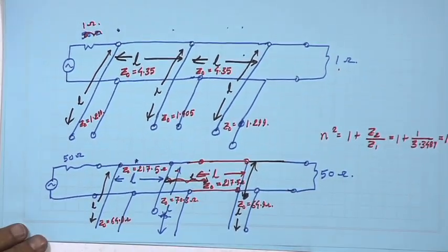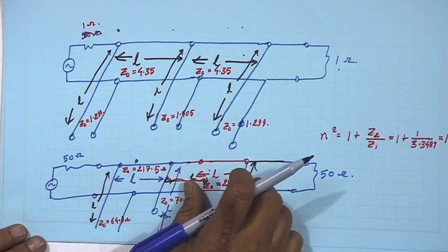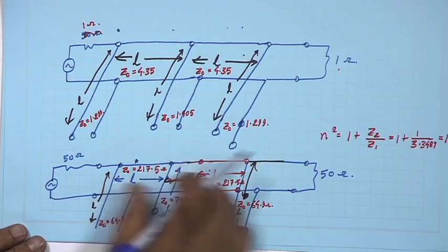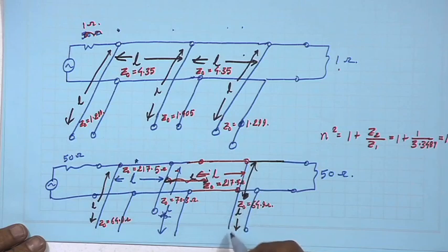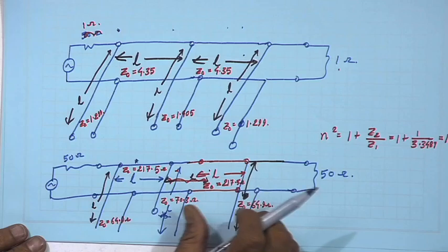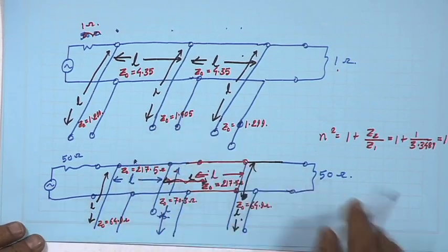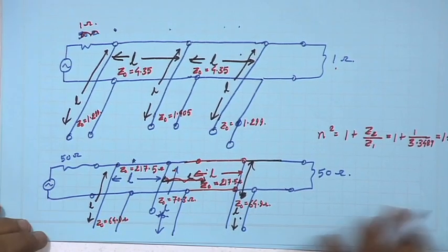Okay. So you see I have now 3 stubs, and 2 unit cells, but they are not stubs, they are transmission lines. These 3 are open circuited stubs. This is for the first inductance, this is for the capacitance, this is for the inductance L3, and these are unit cells. So now with these lengths the sizes are manageable. I have separated them. Now, these unit cells are called redundant sections, they are matched.